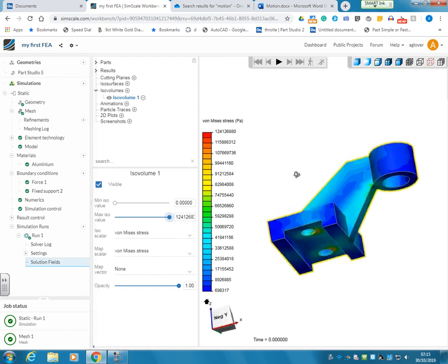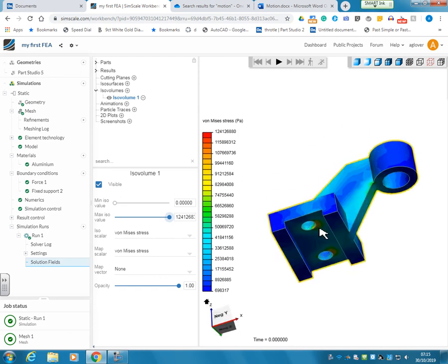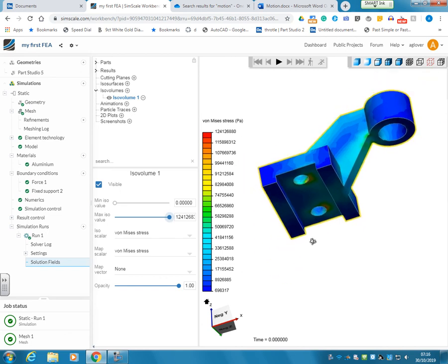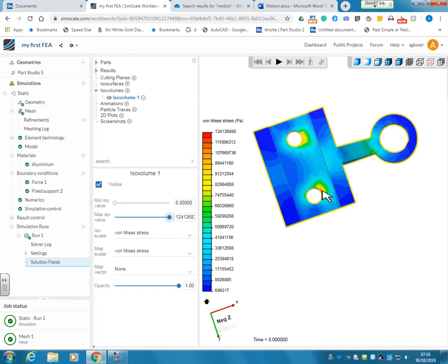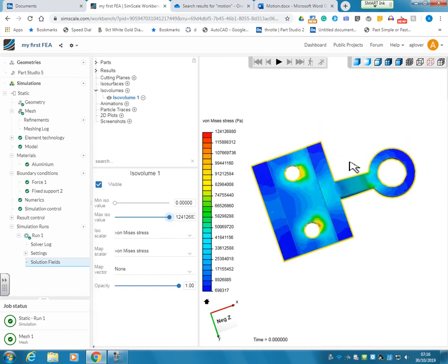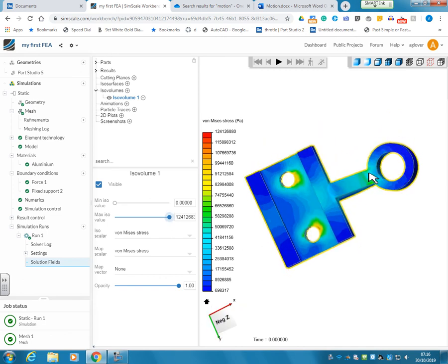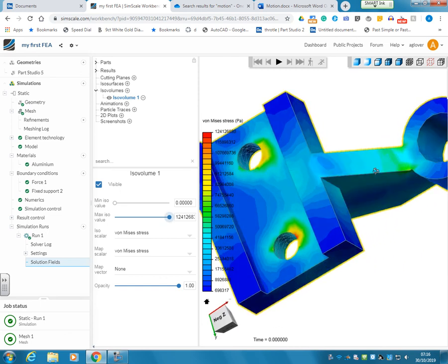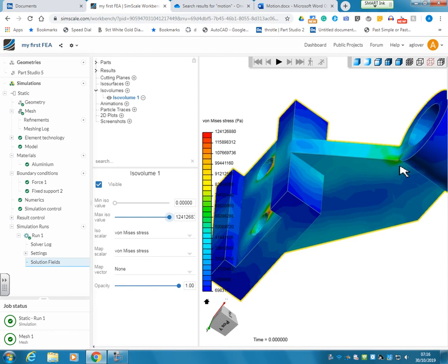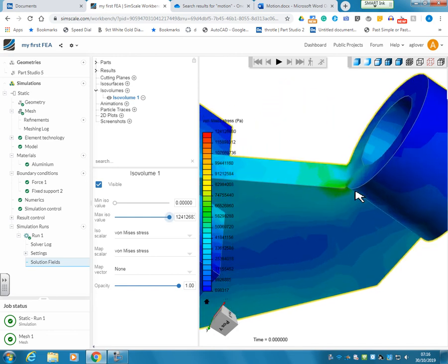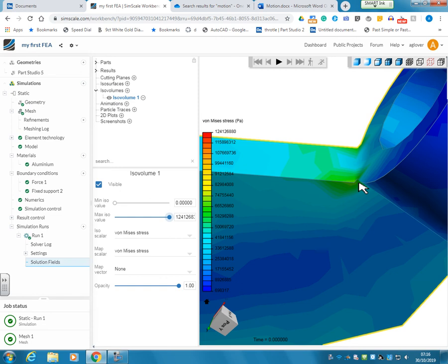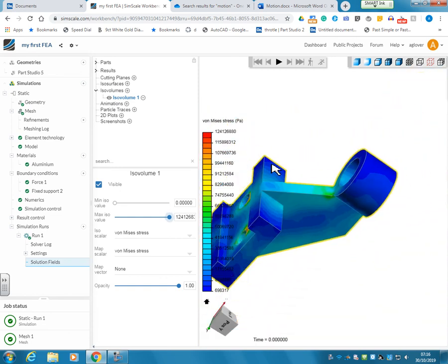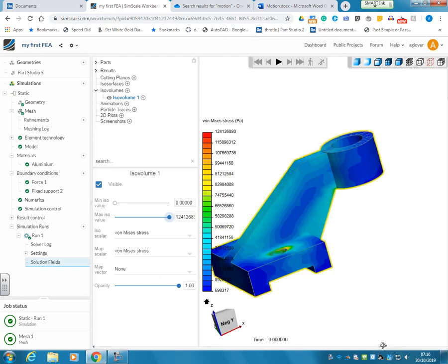If we rotate underneath, we'll see force being applied there as well. In fact, quite high forces. And then also underneath here, doesn't come as much of a surprise. There's quite a bit of force there in this corner. It's a bit of a stress raiser. We can see that. Now there's a few ways we can actually see inside where it is.